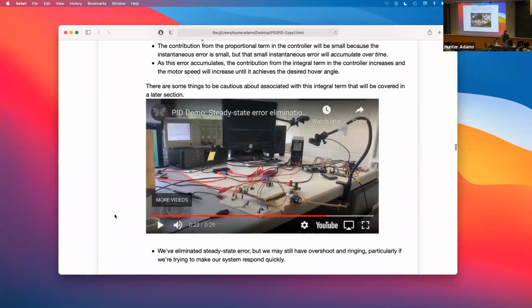This is one of those things, by the way, that when you're working on control problems, was bothersome at first to me, because it's not a problem necessarily where you're trying to find right answers. There's not necessarily a correct proportional, integral, and derivative gain value. What you have instead are requirements. For problems like this, those requirements are usually how much overshoot are you willing to tolerate?